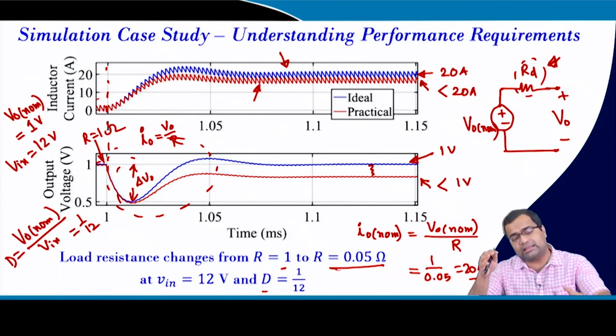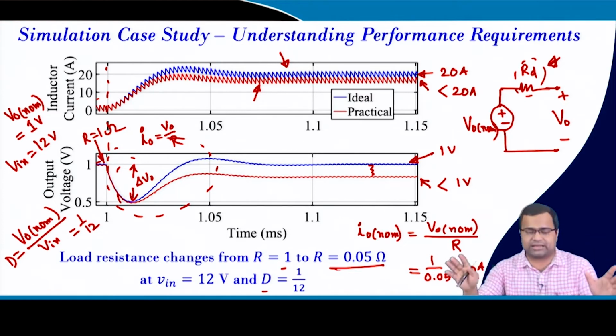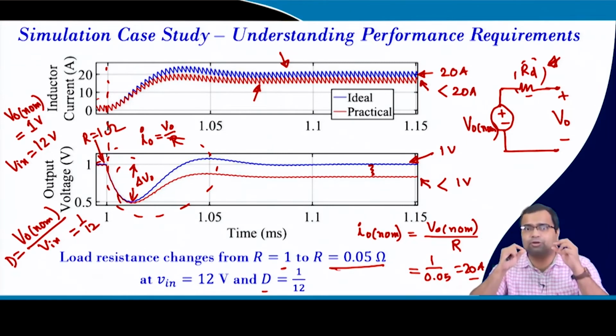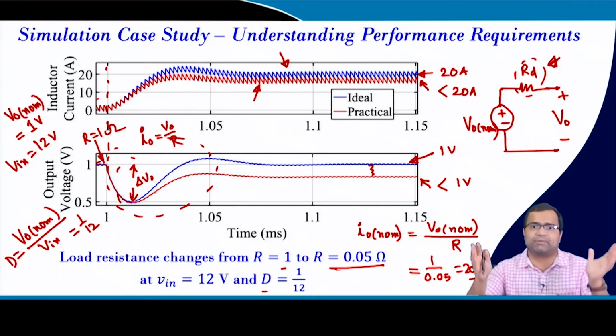And this voltage will be supplying a digital processor, where such a voltage difference can completely lead to malfunction of the digital circuit, because the digital circuit has a certain noise margin, that means a certain voltage range for which the logic level will be treated as 1, and if you go beyond that, the digital circuit will start malfunctioning.